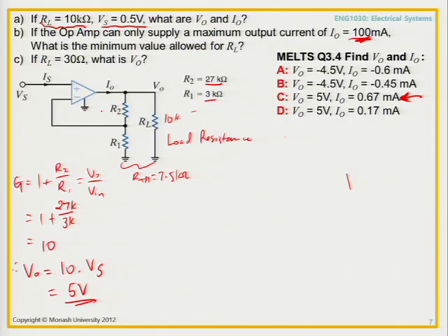And over here on this side, you've got 30 kilo ohms. Let's say that's 30K. So if I start reducing this value to 10 kilo ohms, and let's say we've still got the same gain, it's 5 volts. If this is 10 kilo ohms, the current drawn is 0.5 milliamps. What happens if I make this 10 times less, make this 1 kilo ohm? What current comes out? A bit more, right? 10 times more. So you start to get 5 milliamps.